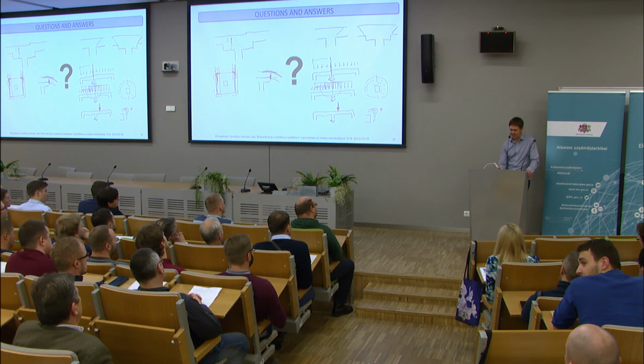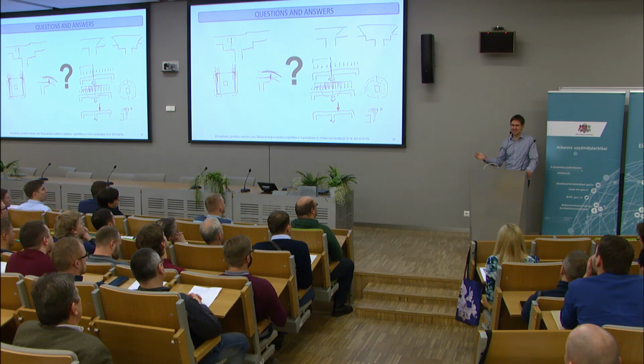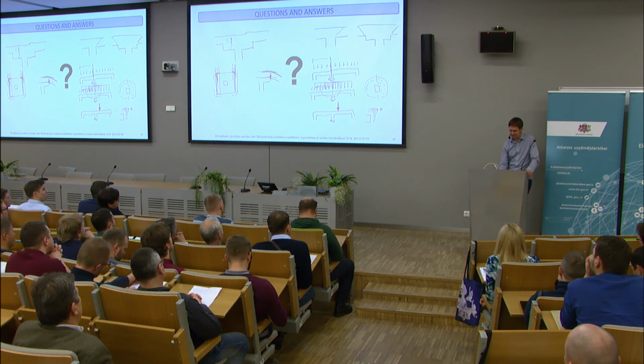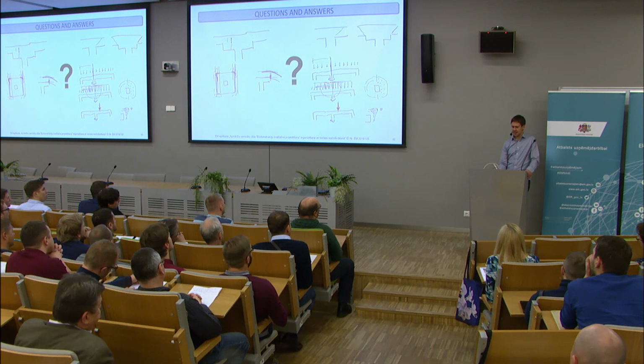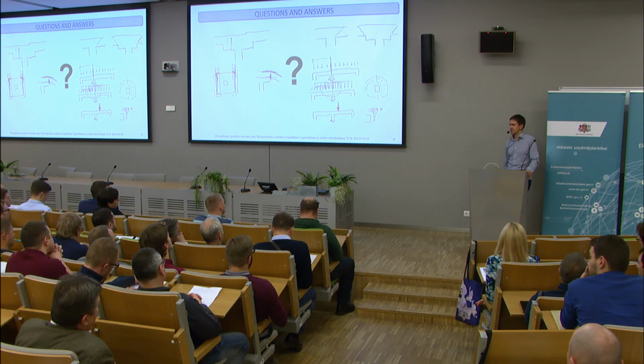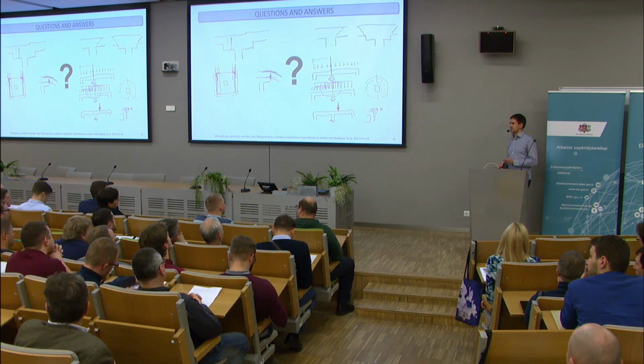Without beta then? Well, beta will already cover it. Beta is this. And then if you want to make it more precise, you can do nonlinear flexure analysis, and you will be able to redistribute it. But for that you need to do nonlinear analysis if you want to be precise.